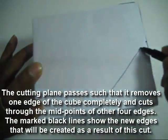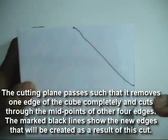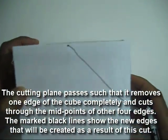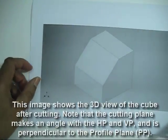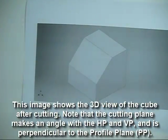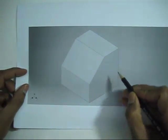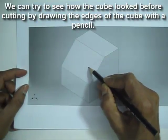So the cutting plane passes such that it removes one edge of the cube completely and cuts through the midpoints of other 4 edges. The marked black lines show the new edges that will be created as a result of this cut. So this is the 3D view of the cube after sectioning or cutting. These are the edges of the cube, and this part has been cut, so new edges have been created.